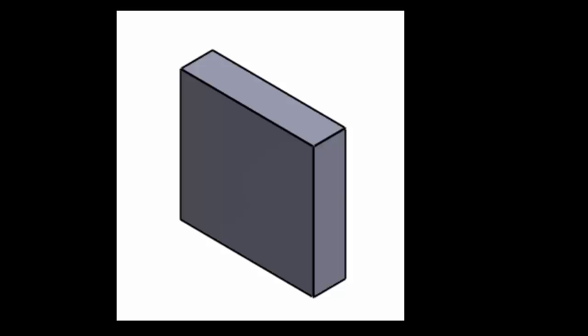One of the most commonly used tools in all solid modeling is Extrude. This tool requires you to provide a sketch and then give that sketch a thickness. I want to demonstrate making an extrusion. We will use Inventor to create a simple block as shown.